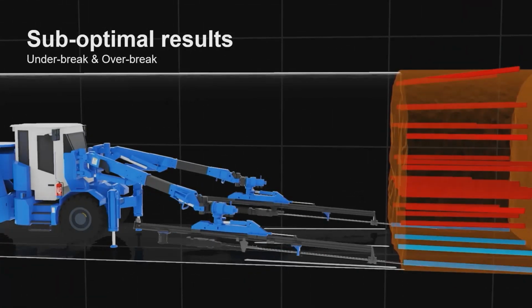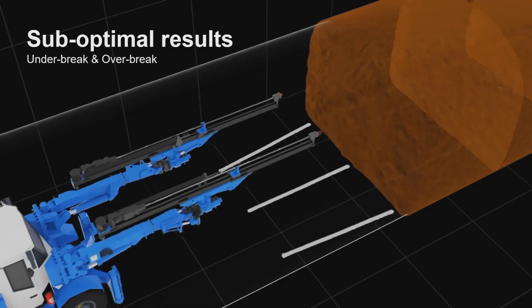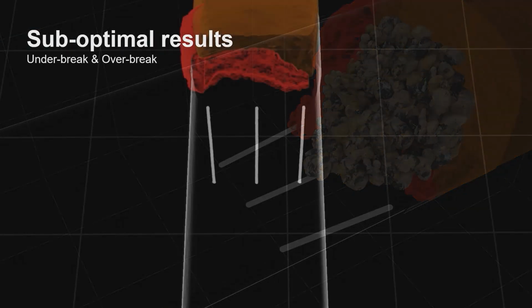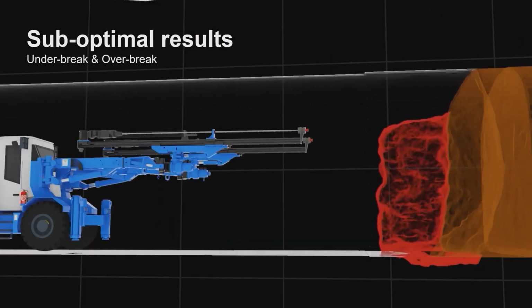These suboptimal parts that we see is underbreak, so we're not getting that full design volume. We see that through tightening in the shoulders and the backs and dishing at the face. This impacts the advance rate of the client, and in more extreme cases requires remedial drilling, impacting the development cycle process. The second one is overbreak, and as simple as you can see here, when we're blasting more material than required, we're increasing that load and haul cost for the client or contractor.